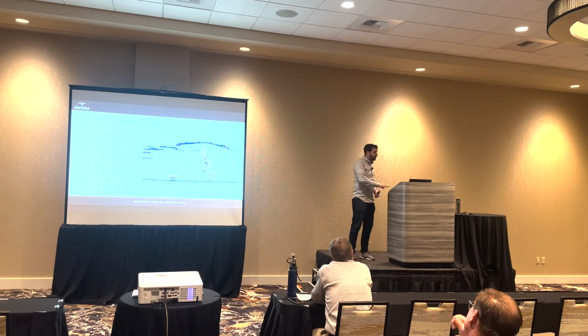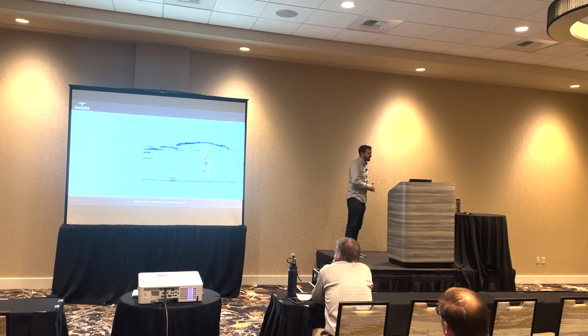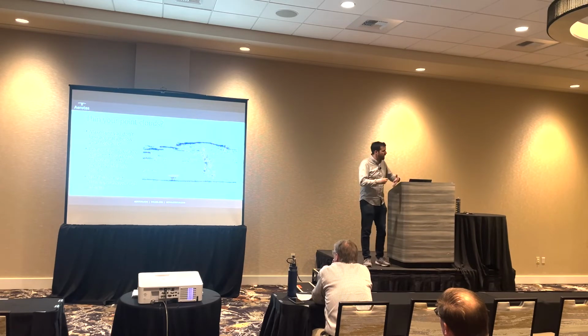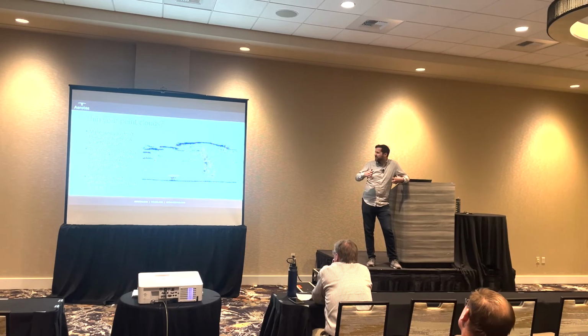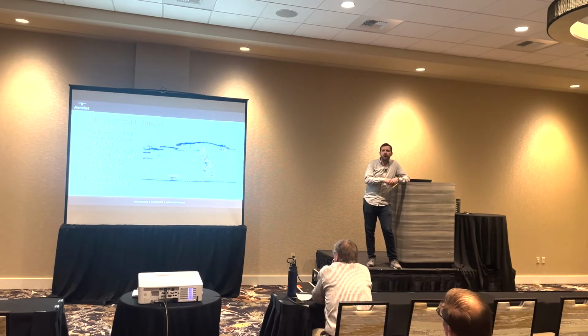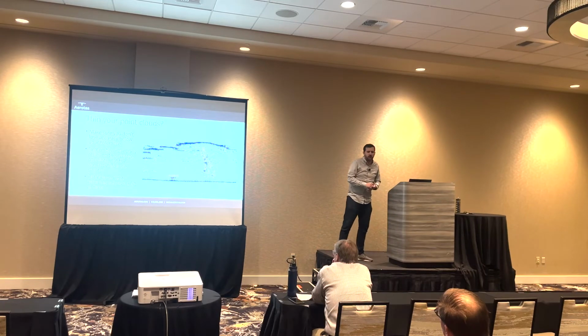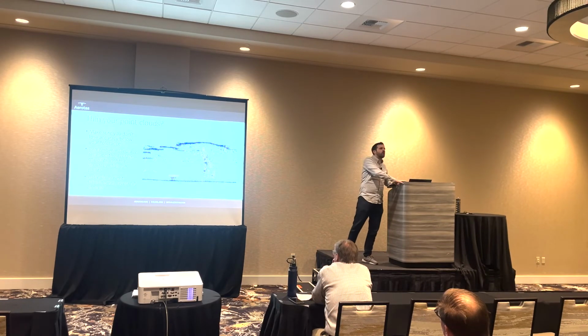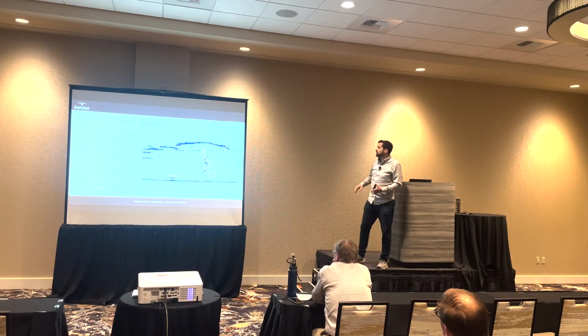And this is much like photogrammetry. You could buy your $16,000 computer and it's still going to struggle with a 3 billion point cloud or something like that. So one of the solutions out there is whether or not to thin a point cloud. This is one of those points in the workflow where I'll acknowledge that there's still a lot of debate about what the proper methodology is. Sometimes we do thin point clouds. Usually we try not to, because it can save time, but you also give up much of the resolution that you've got. So you want to make sure that you don't lose accuracy.